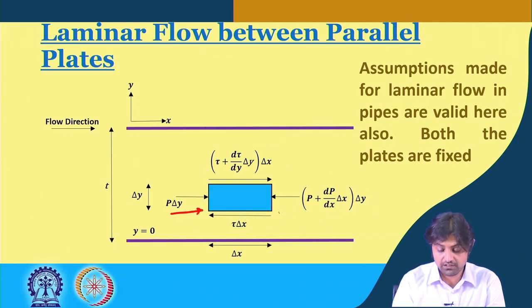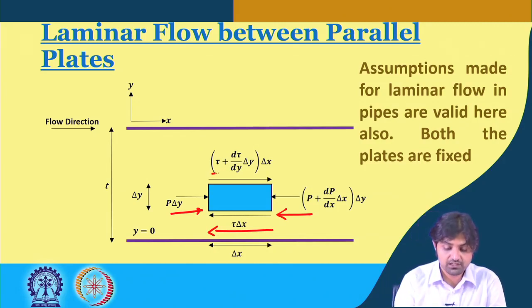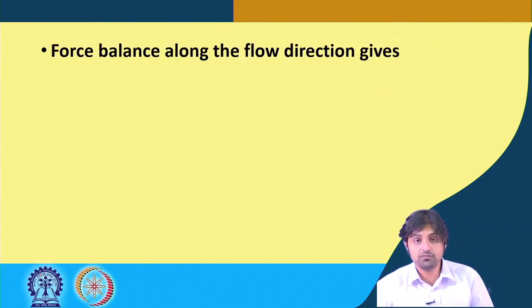As you can see, pressure force is acting in this direction, and pressure force is acting in this direction. On the bottom side, the shear force is acting in the negative x direction, and here it is acting in the positive direction. So, with this in the background, we start to write the force balance analysis along the flow direction.